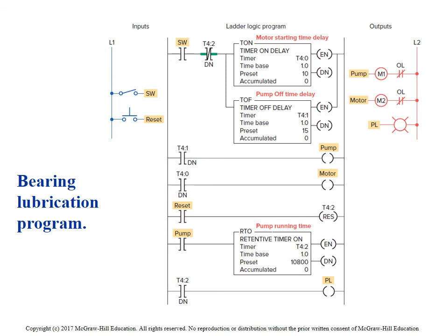they needed the lube pump to turn on for like 3 seconds or something, or 5 seconds. And so what I'd do is I would hit the count of 500, say, trigger a one shot, and that one shot would trigger the off delay timer. So that one shot turned on the off delay timer, and the off delay timer would be set for 5 seconds, and it would lube the shaft for 5 seconds. Works pretty good.